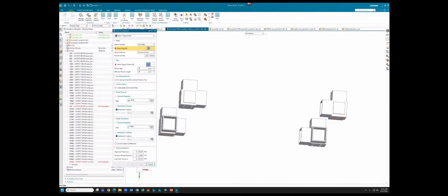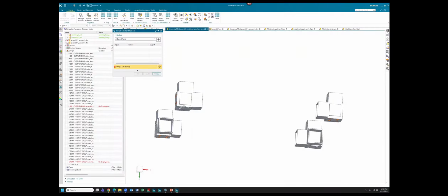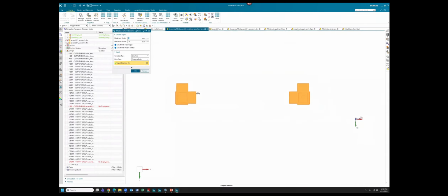And for the head side, it's looking for cylindrical edges that it wants us to select. So instead of manually selecting 16 edges here or trying to draw a box to do that easily, what we're going to do is leverage our smart selector methods. And these are really powerful as well that I really want to make sure people are aware of. So these are essentially selection tools where, for example, I can tell it I want you to select circular edges. I can tell it which geometry I want it to select those relevant edges on.